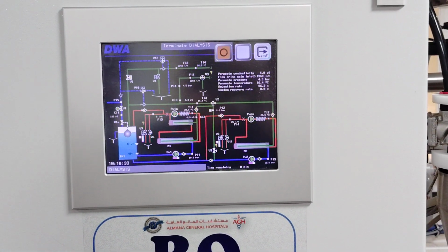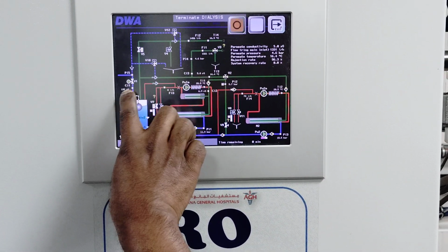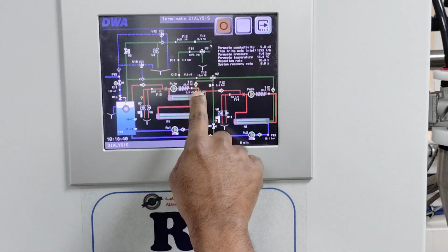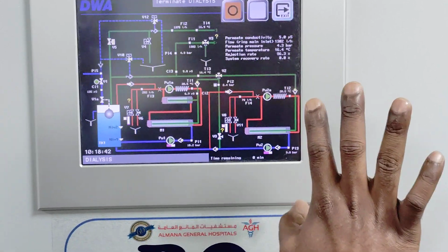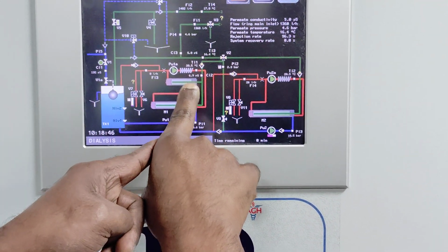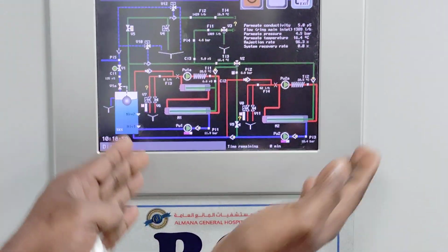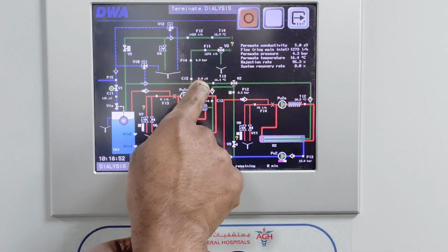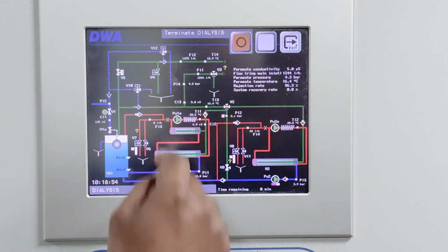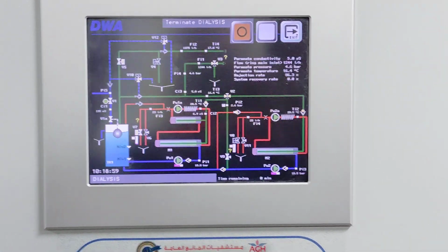Okay, loop temperature. Like conductivity, inlet conductivity 135 now, it's showing here. Okay, then this is T1 conductivity, then T2 6.9, output temperature of the membrane 6.9. This is input, this is output. Okay, conductivity of after the membrane. Then again after the membrane, everything passed, it's going to the next step. You can see 5 conductivity. There are 3 different conductivity sensors over there, so 3 places.